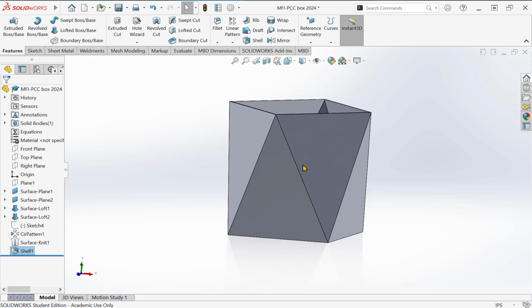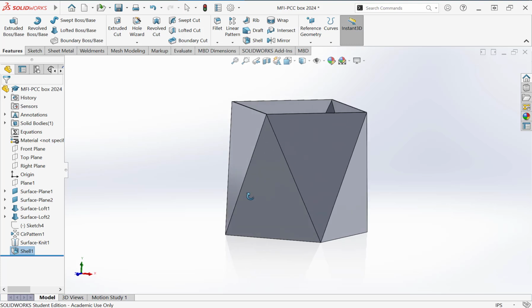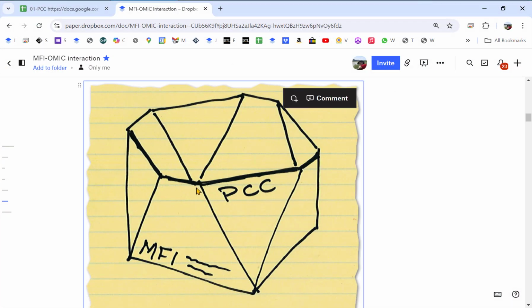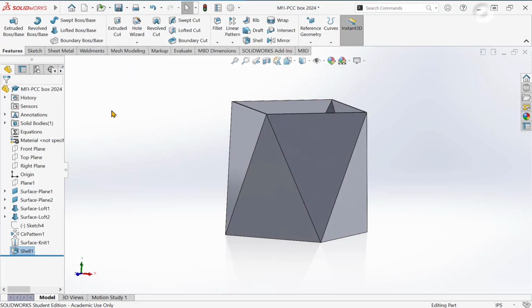The next thing is, we didn't really intend for the box to be this tall. This is just the primitive shape of the box. This is the easiest way to get the overall shape, was to build this taller complete box. Looking back at our picture, we see that it is foreshortened by some amount, and we don't know exactly how far that is yet. So we'll just take a guess and we'll change it later. To do that, all I really have to do is draw a line across some section here in the middle and position that line where I think the cut should be, and then we'll do an extruded cut feature that will remove the top of the box.